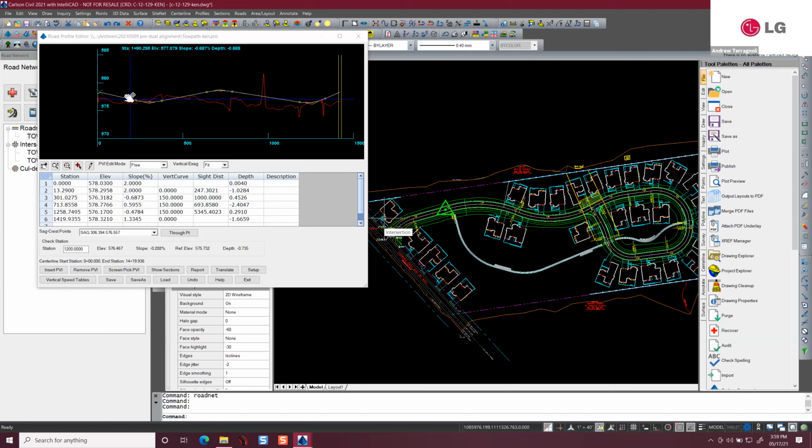It's really clayey soil, but the bearing capacity is the key. A lot of wetlands have clay, which is okay for bearing. But I did another one of these where the soil was so spongy I needed a settling plate, and we needed to go out there weekly to see when the consolidation was starting to reach its limit.